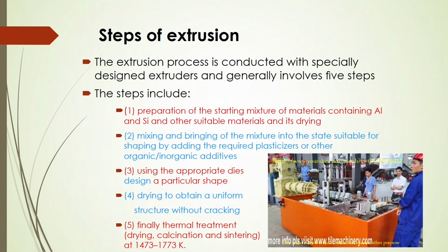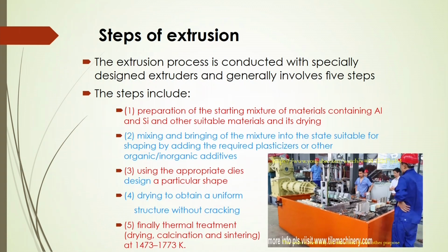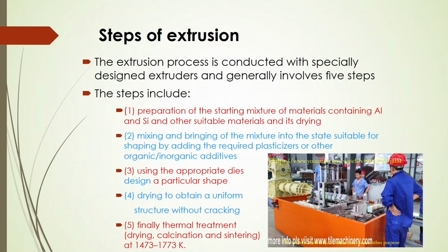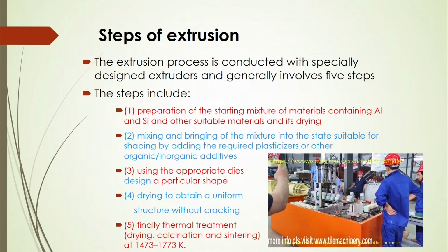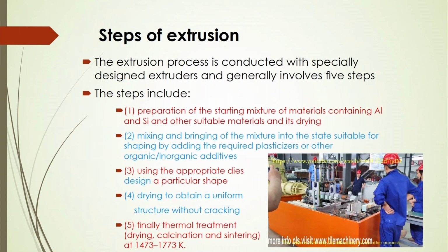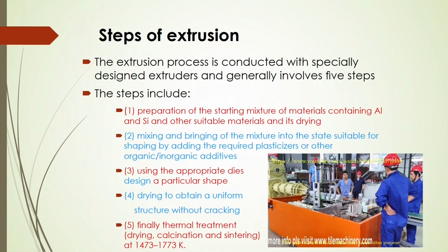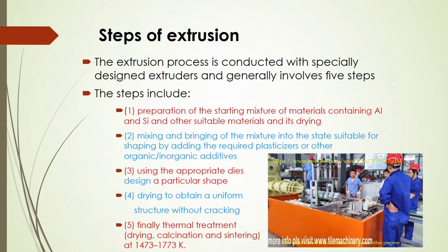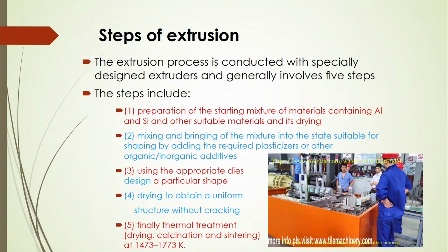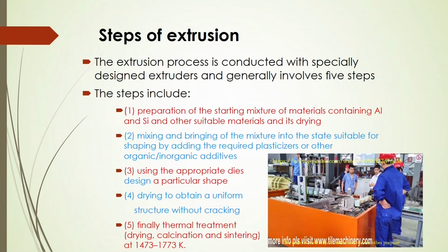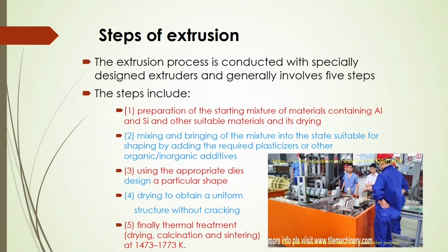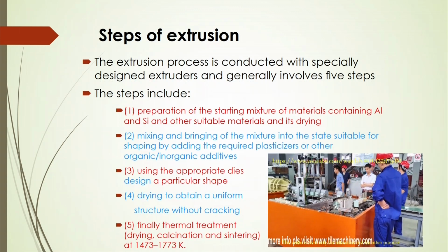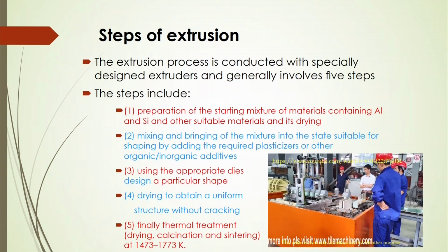After that, you have to mix those materials well and bring the mixture into a state suitable for shaping by adding the required additives, called plasticizers or other organic or inorganic additives. And after that, using an appropriate die, you have to design the structure of this monolith into a particular shape.